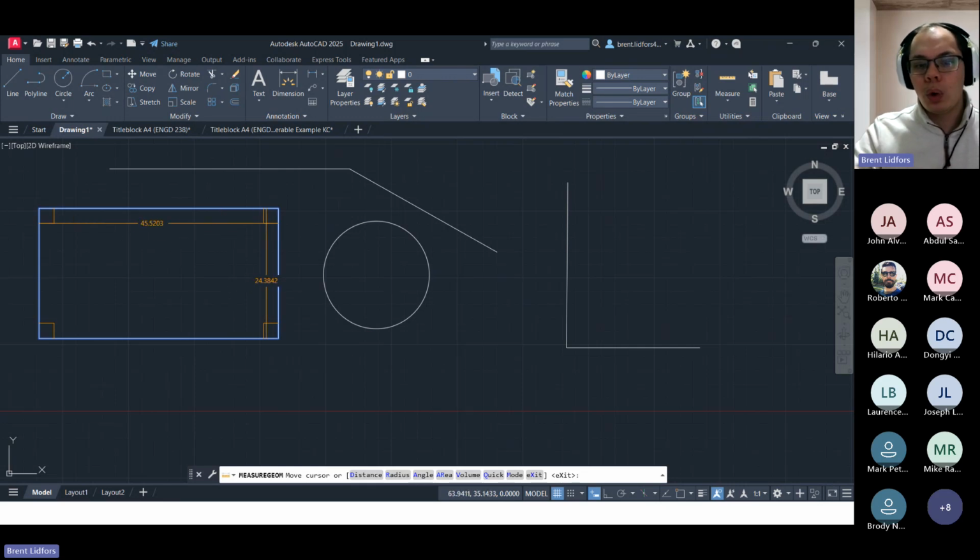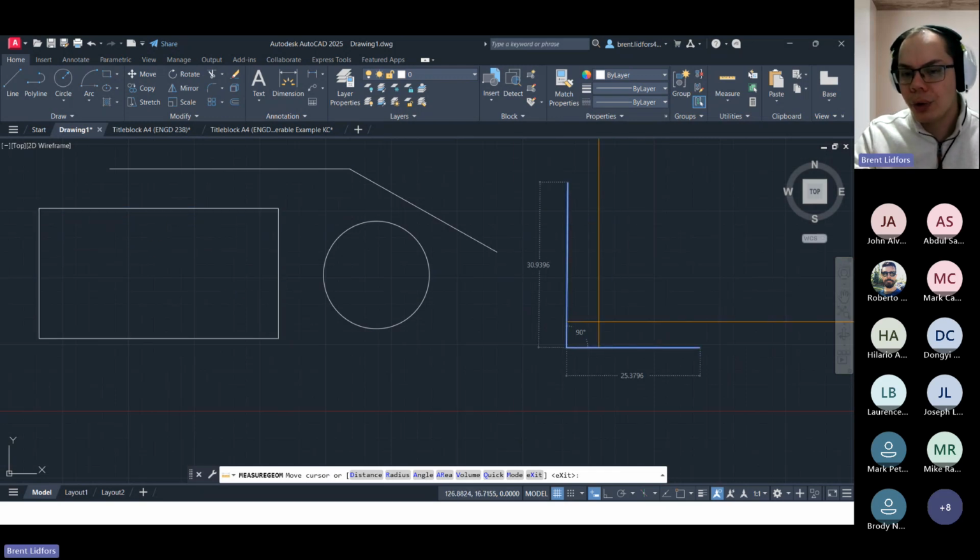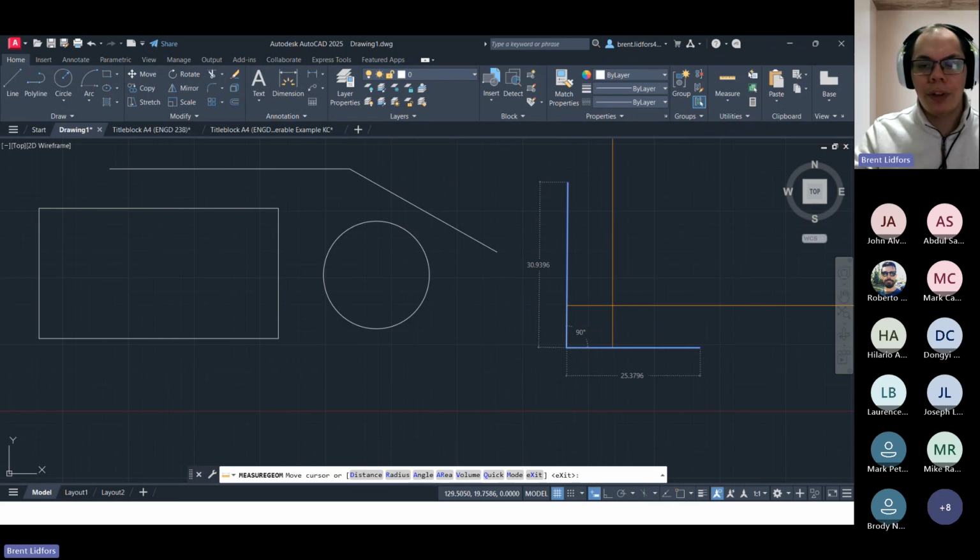So it's giving me these orange boxes in the corners. Whereas I come back over here to these two lines I just drew, it's saying it's 90 degrees, but I know it's not exactly 90 degrees because there's no orange box. Okay, so that's an extra helpful thing with quick as well. It can verify 90-degree angles pretty well.